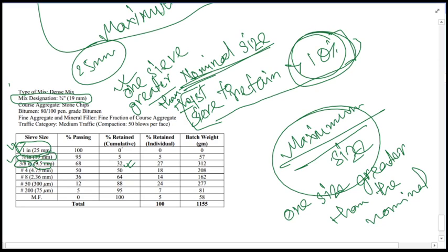And as the maximum size is this one, we will calculate everything from this. Maximum 1 inch, we will always take it so that all the aggregates passing through this 1 inch are taken as the maximum size. Nothing will be retained here. You will see this one is retained, although it is cumulative, just ignore this.